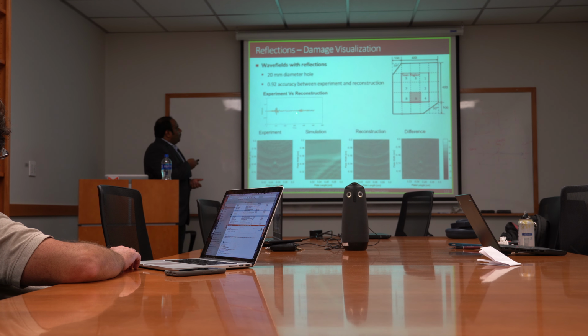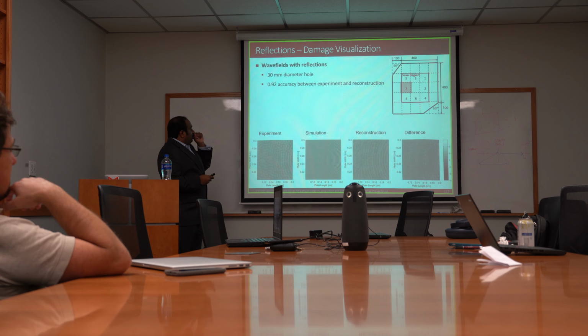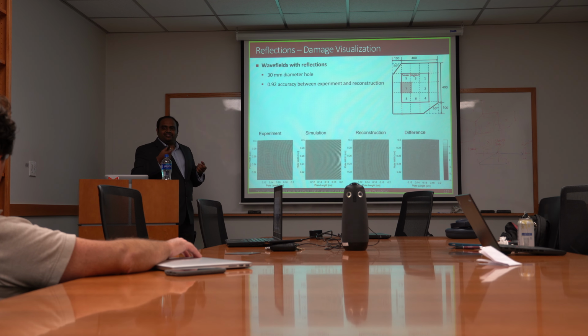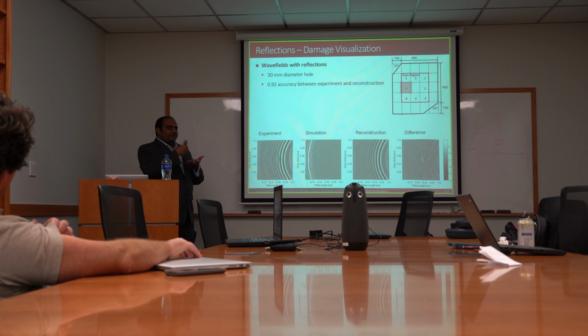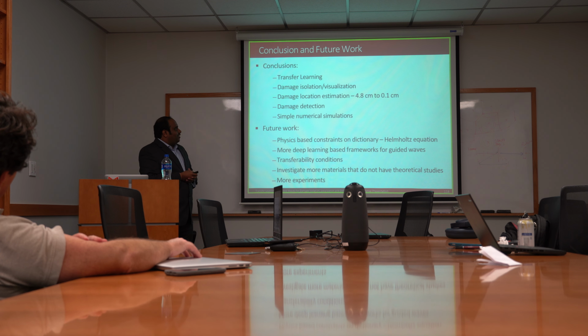And here, what I want to show from this slide is, this is the incident wave, and this is the reflection from the boundary. So all I want to say is that you are even reconstructing the reflection, which was not possible in the prior method. Another different region with different sizes of hole, and this is a bigger hole. You can see the speed of the asymmetric mode decreases as it enters that hole, because different thicknesses travel at different speeds. When there is a smaller thickness, the speed of the wave decreases, and you can clearly see that happening in the subtraction.